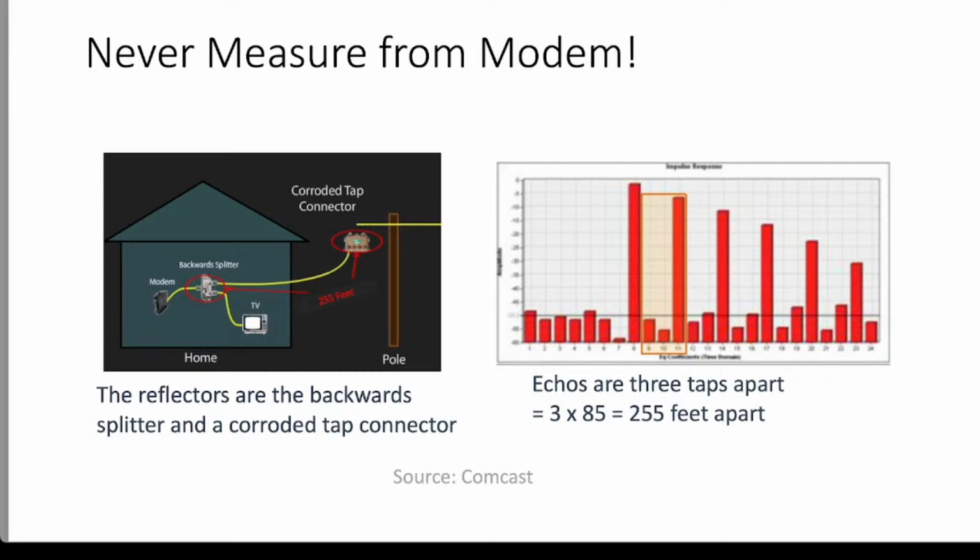Correct. And just to explain, verbalize what's happening with those digital taps on the right side, every cable modem, well, DOCSIS 2.0, 3.0, and 3.1 cable modems, have a 24 tap digital pre-equalizer in them if they're using SC QAM channels in the upstream for 3.1 cable modems. And that's pretty much what we're seeing there.